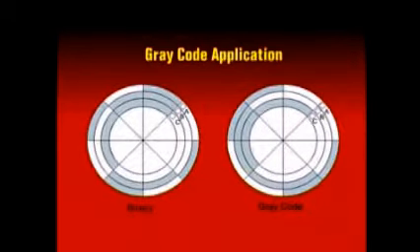Thus, LED connected to brush B lights up indicating binary 010. Thus, at any instant of time, the LEDs indicate the angular position of the rotating shaft in steps of 45 degrees. Assume that the 3 brushes A, B and C are not aligned properly and brush B is slightly ahead of brushes A and C.